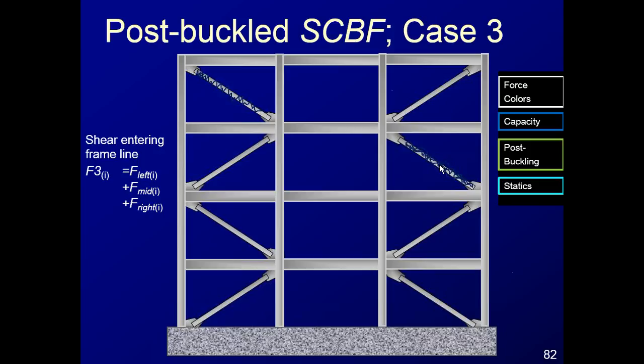In tests, if you rack the frame long enough, the braces essentially fracture and maybe even disappear, they become totally ineffective. But for our purposes, let's assume that these braces lose a lot of their effectiveness in compression, but are still participating a little bit.